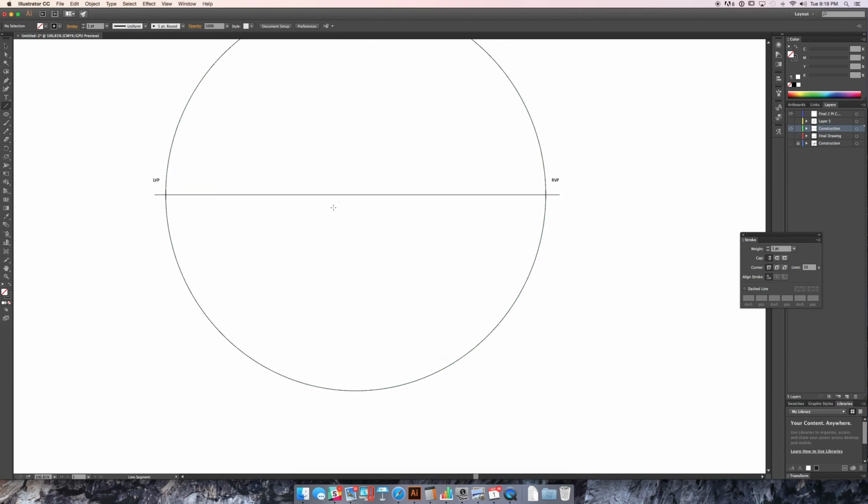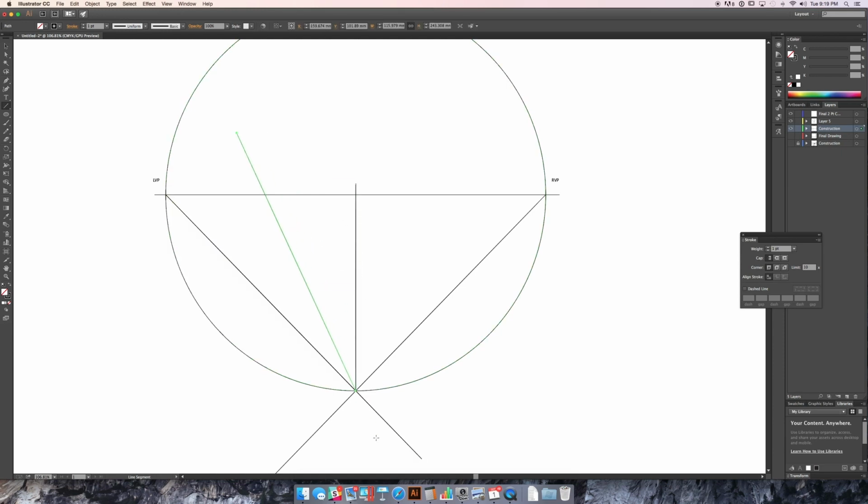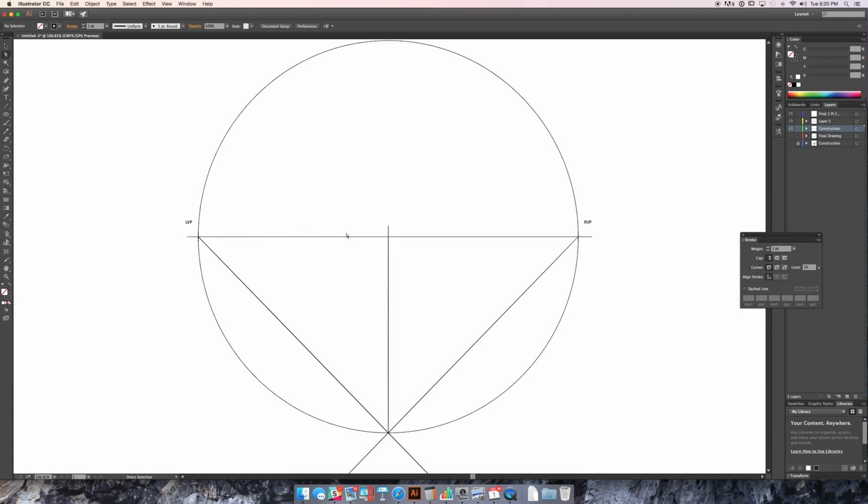Okay, generally speaking, there's a cone of vision of 60 degrees. So if I want something to seem fairly well adjusted and seem normal, I'm looking at probably a viewing angle of something like that. So that's typically where I'd want my cube to be. But because we're designers and we're going to be sketching somewhat interesting perspective views, we're going to push outside of that just a little bit. But we're not going to push outside this circle because that's where real distortion will happen.